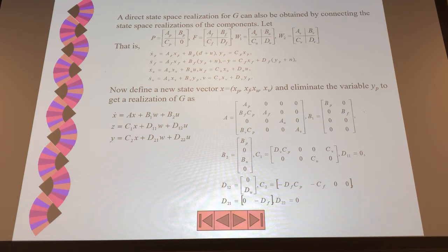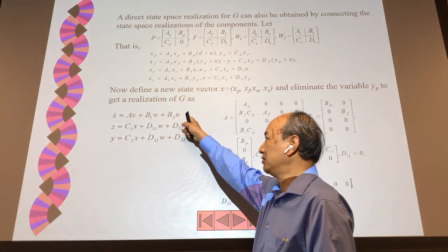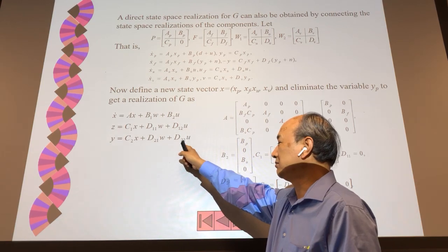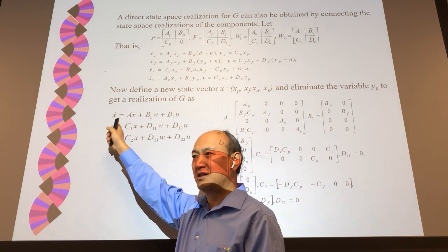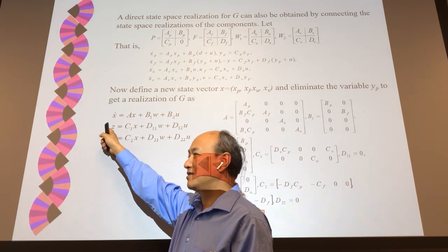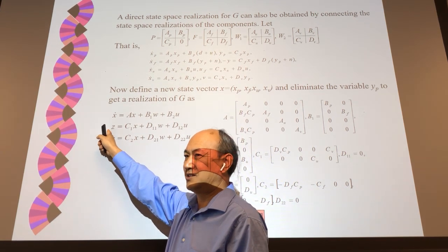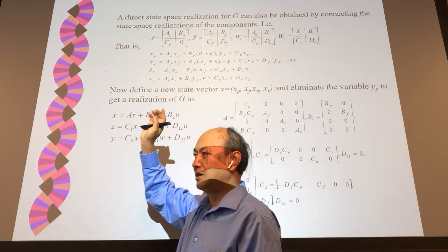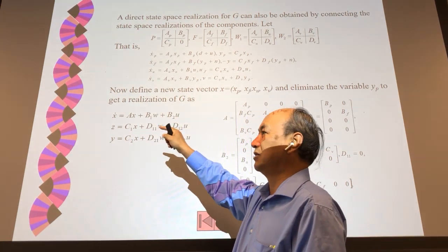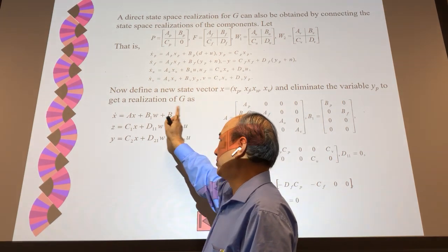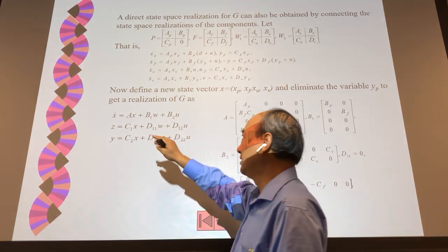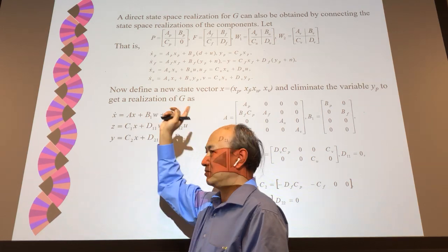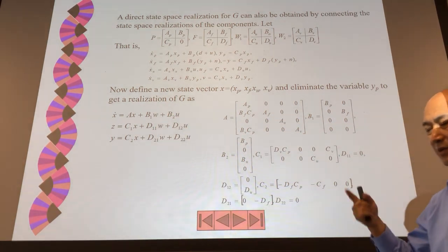So in robust control, we have state equation, output equation, and we have Z, I invented it, I call this output for performance assessment. I use Z for my performance assessment. I only care about closed loop transfer function from my W to Z. I don't care anything else. So performance-wise, I only care about T_ZW, the closed loop transfer function between W to Z.